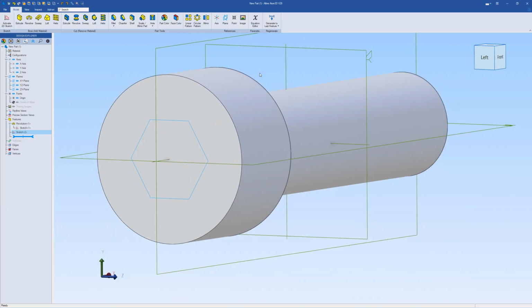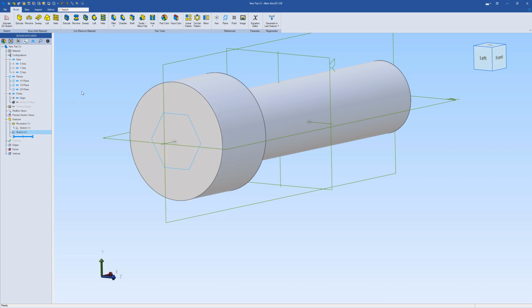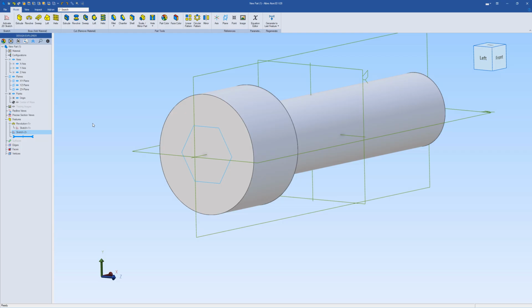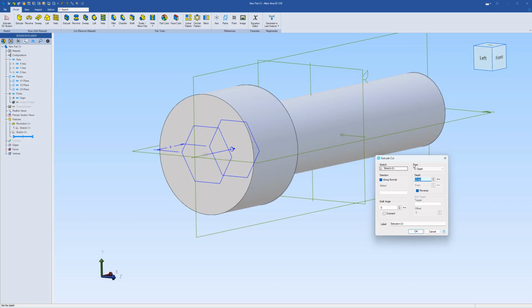And so for this one we want to cut the socket into the body of material there. So we can use the extrude cut option. That's under the cut remove material section, there's an extrude option, so we go into that, and this has defaulted to a negative dimension because we're trying to cut into the part. Positive would be away from the part, so that's correct.